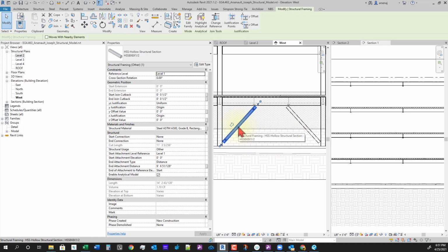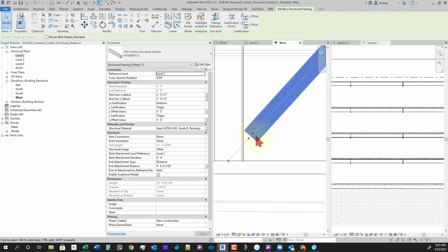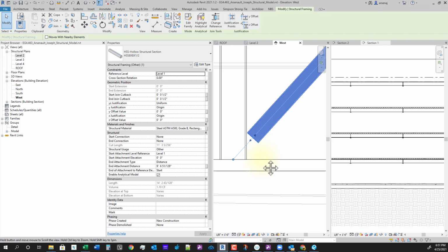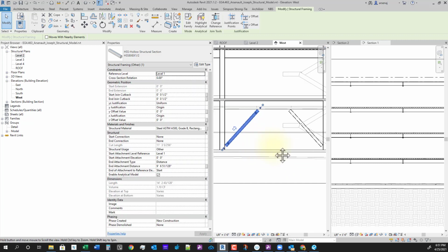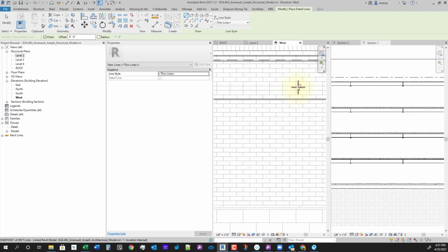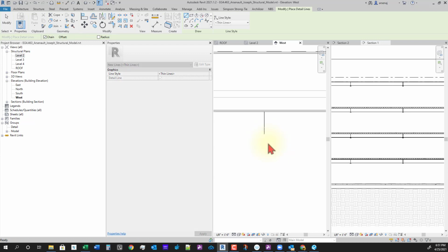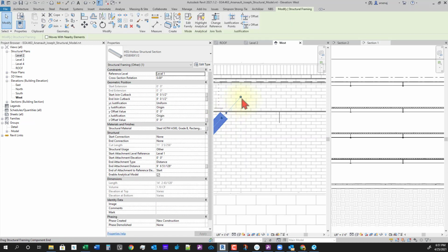So that the brace here is, because what'll happen is there'll be a knife plate here, or it'll be a steel plate that they'll likely cut through the middle of this tube and then weld it there, bolted onto it. And let me see. I think what I want to do is make it centered on this beam. So what I'm doing is drawing a detail line centered on the beam flange, which is the bottom of the beam.